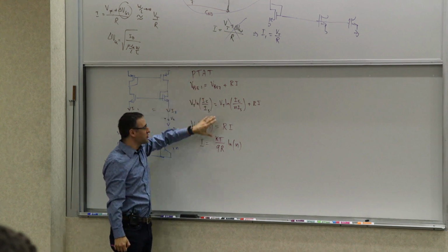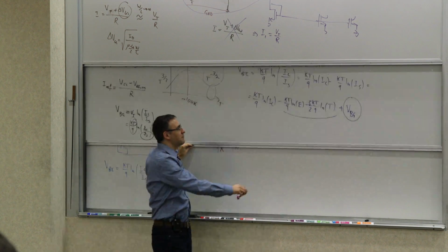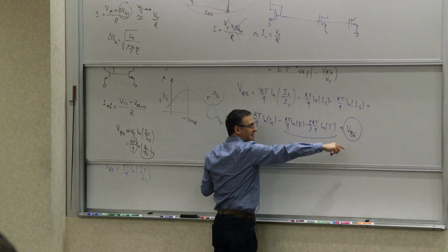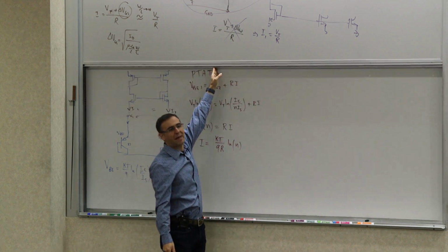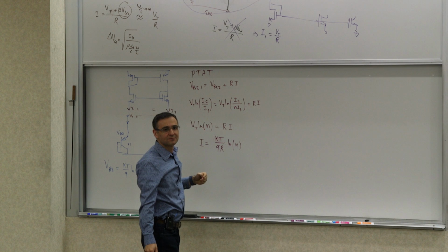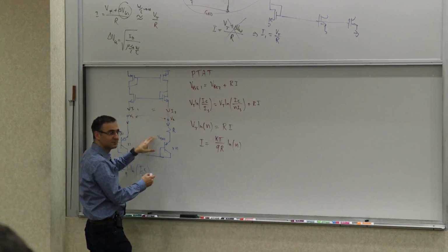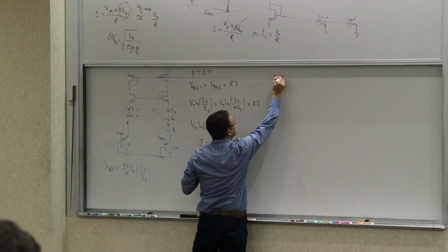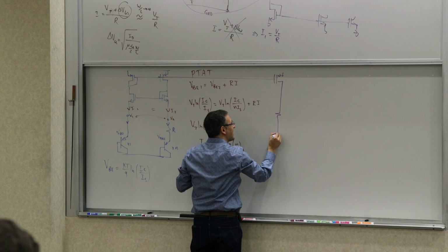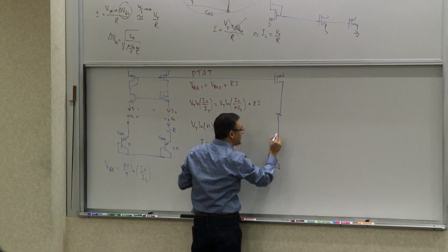If we add a sufficient amount of this to that, it may appear that you may be able to get this thing out. And that's what a band gap reference really is. So you take this PTAT that you generated, and then you copy it somewhere, and then you pass it through a resistor, and then you add it to a VBE.